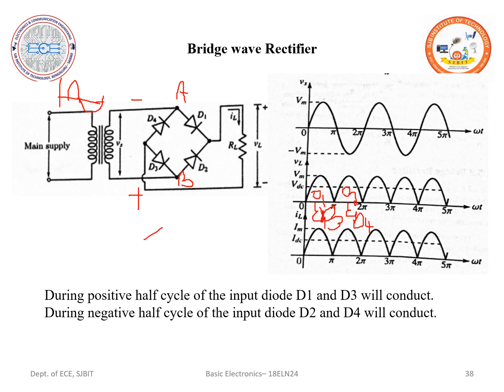That is, if I represent this during the positive half cycle, I can say my diode D4 is an open circuit, my diode D1 is a closed circuit, so continuous. Similarly, my diode D2 is an open circuit and my diode D3 is a closed circuit. This is how my circuit is going to be during the positive half cycle, and during the negative half cycle vice versa. This is going to become a closed switch and these two are open switches.